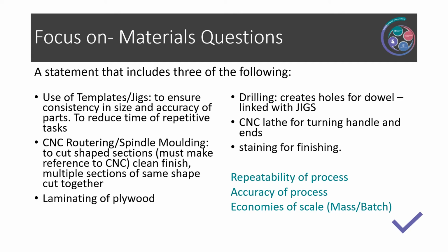CNC routing or spindle moulding has been used to cut shape sections for both the scooter and the high chair. You must make reference to this being CNC. This gives a clean finish, multiple sections of the same shape can be cut together, and again, it's a repeatable process with high levels of accuracy and economies of scale.